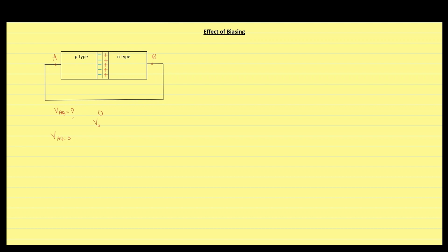But the wire is also making a contact, meaning that majority carriers will flow through the wire, creating another region at the boundary of the semiconductor crystal, which is depleted of charge carriers. The formation of another temporary depletion layer compensates the built-in potential such that Kirchhoff's voltage law across the circuit is satisfied, and this is why the potential drop across the two ends of the wire is zero. And this is the same reason why we cannot measure the built-in potential through a voltmeter.